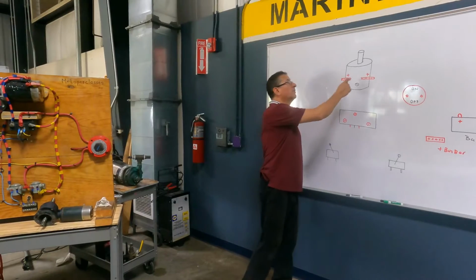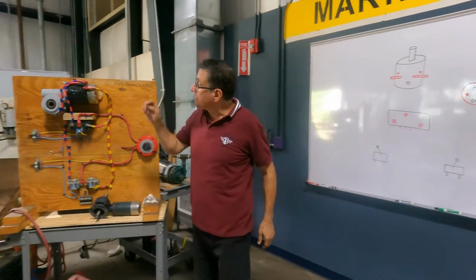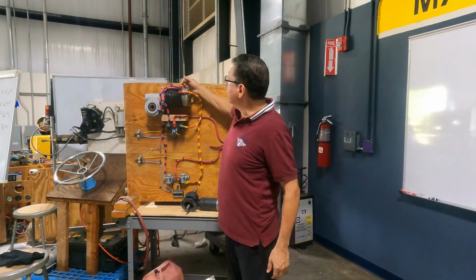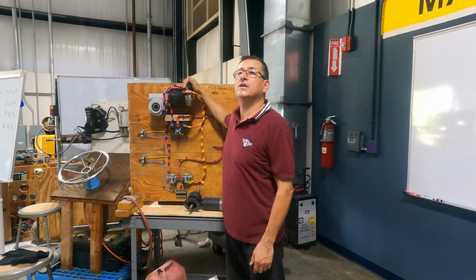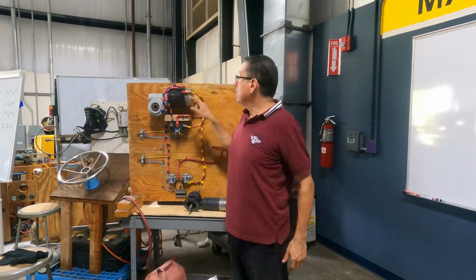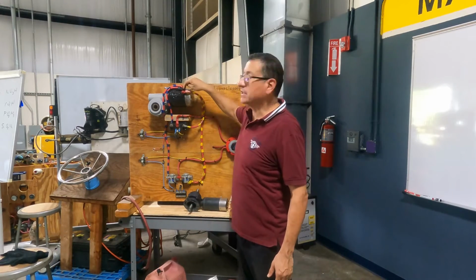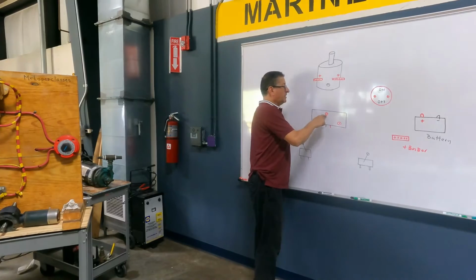I have the reversible motor. All the reversible motors have two positive terminals. Look at this. One positive terminal here, another positive terminal here, and the negative in the middle. In some cases, the negative is in another place on the body. No problem. Positive, positive, and negative. And the solenoid control box, positive, positive, and negative.